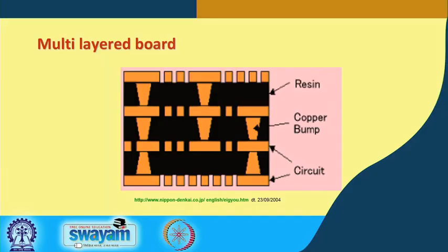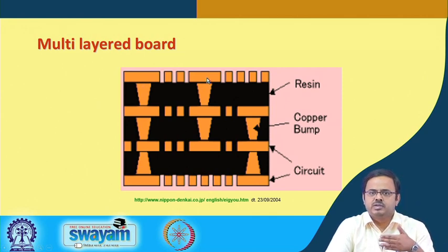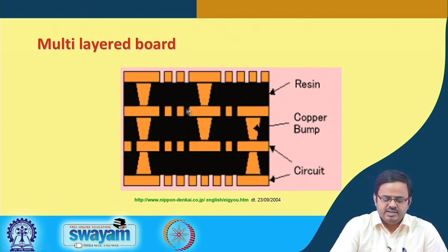Before that, just a recap from last time, we talked about multi-layer boards, where we said that there are internal wiring traces. This picture is a cross section of the motherboard. If you take this green thing that you see, a few millimeters, and take a cross section and look along the side under a microscope, this is what you should be able to see. These are internal layers. You can see this copper, these are wiring traces.